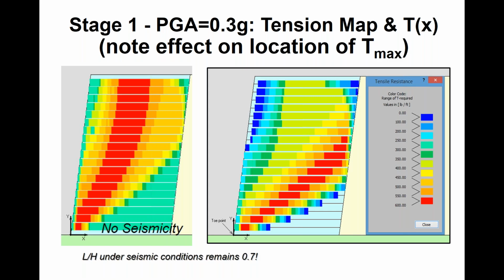That band shifts wildly. Now, if you've done any seismic design for slope stability or reinforced slopes, your intuition tells you that whenever there's some kind of horizontal pseudostatic coefficient, our surface deepens, or a reinforced surface deepens.